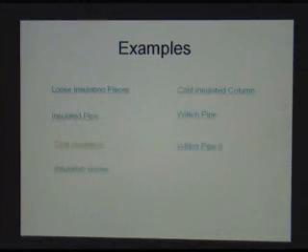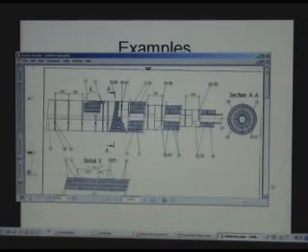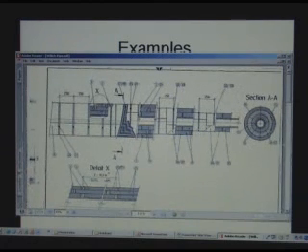Quite often we work overseas and we're not sure that our contractors are able to do the installation right. Click on Village Pipe, for example. Yeah, this one is good. So we ask them to supply their own drawings or sketches how they do the installation. You can see here all the details, number of layers, expansion joints, and then all these little numbers point to the materials you plan to use. This is a good tool for us to make sure he understands the scope and can do it right.